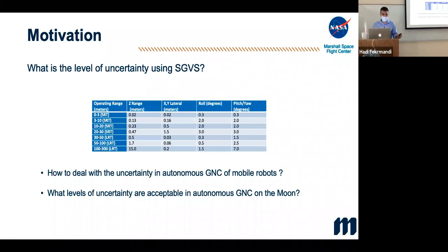If it is 0 to 3 meters, then it has a 3 sigma error of depth estimation of 0.2, which means 2 centimeters for the first 3 meters. That actually is really good. And then up to 30 meters, with 0.747, that's like half a meter of error in distance at 30 meters, and also the same type of error that has been shown for X and Y.